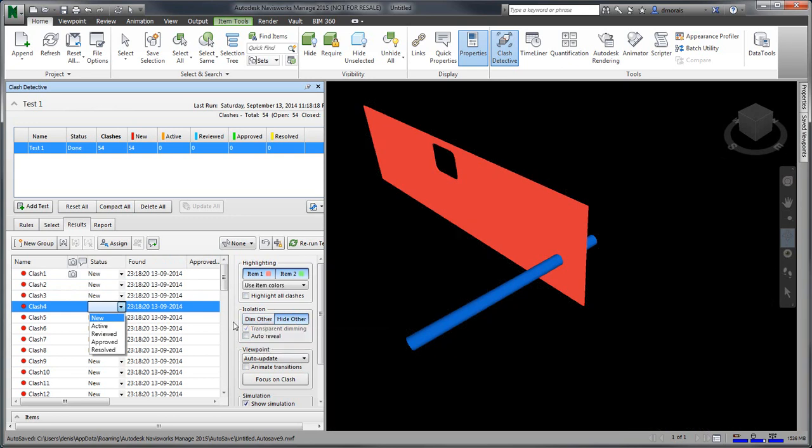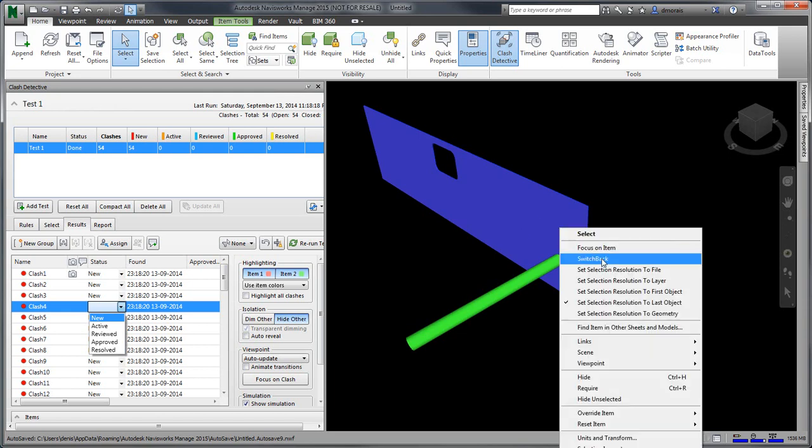One thing I really want to show you is the management of this. So if you have this piping system that comes from site 2, and I'm dealing with a structure that is on my site, how do I actually add a penetration to that? How do I get this information that was combined in BIM 360, downloaded into Navisworks, and how do I open up my authoring tool? Well, with Navisworks, because it's integrated with Ship Constructor in the project, you can simply select this part where you want to create a penetration, and you can right click, call SwitchBack,